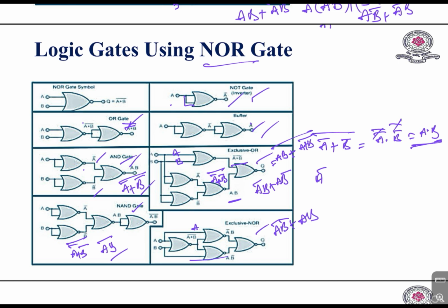So here we are taking A here and B here, and we have to take A plus B whole bar, and here also B plus A plus B whole bar we need to take, and by doing this with one more OR gate, by simplifying this you'll get A bar B, and by simplifying this you'll get A B bar, and again this NOR operation is nothing but A bar B plus A B bar whole bar, or else you can take that complement as the XNOR gate.